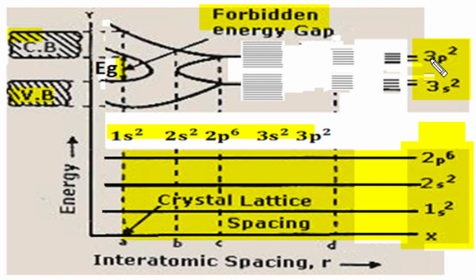We have 4 filled energy levels, 2 in 3s and 2 in 3p, as 4 discrete lines here, and we have 4 vacant energy levels in this 3p, as 3p can occupy in all 6 electrons, but we have only 2 filled and 4 vacant energy levels in a silicon atom.